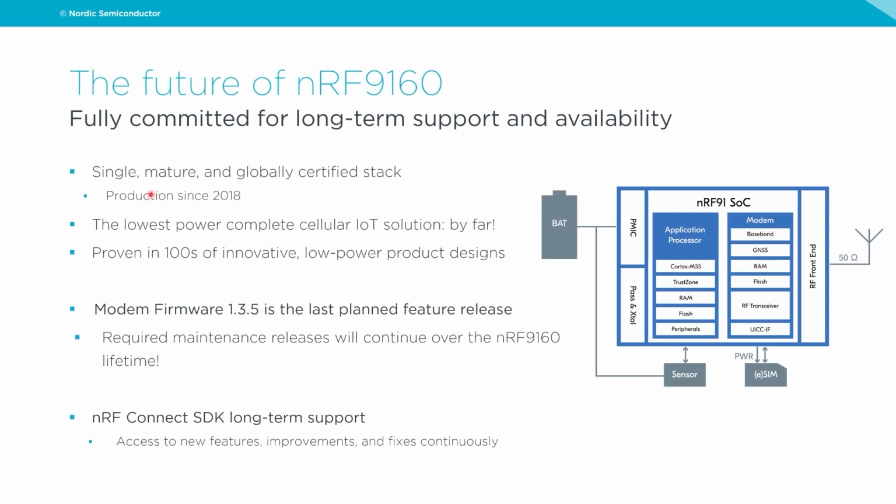So the 9160 is our most mature device. It has been in production since 2018, and we're fully committed to support it long term and to make it available. However, the last release of the modem firmware, which was release 1.3.5 that we had, I think, mid last year, was the last planned release where we have new features. We'll continue to make maintenance releases throughout the nRF9160's lifetime, but there won't be new features coming into this device.